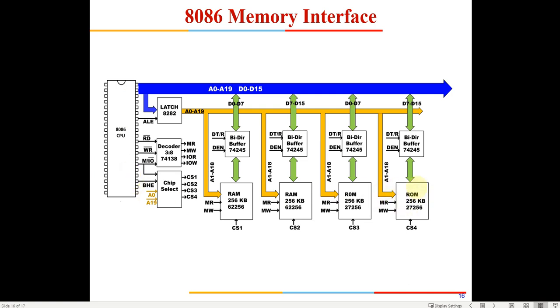That will also be there, because with switching on of the power supply, if the 8086 does not have any program, it is difficult to initiate it at all. So you will have a ROM which is generally pre-programmed and available on the motherboard, and then you will have a RAM where you can do your programming. I am giving just an example: an easy way is to split the memory into 2 equal halves, 1 half for RAM and 1 for ROM. It's not necessary to do it like this, but it is one of the possibilities.